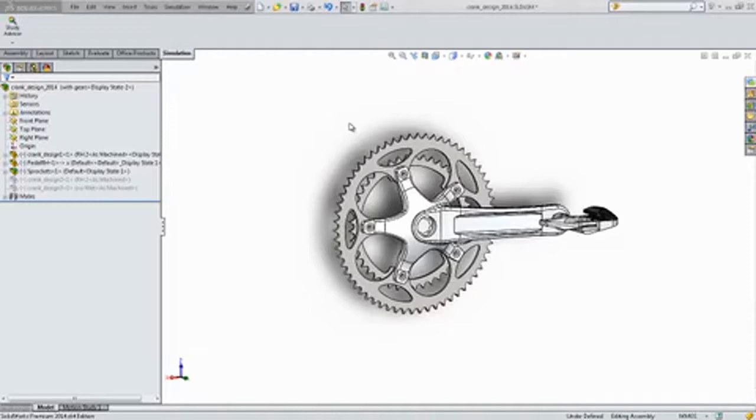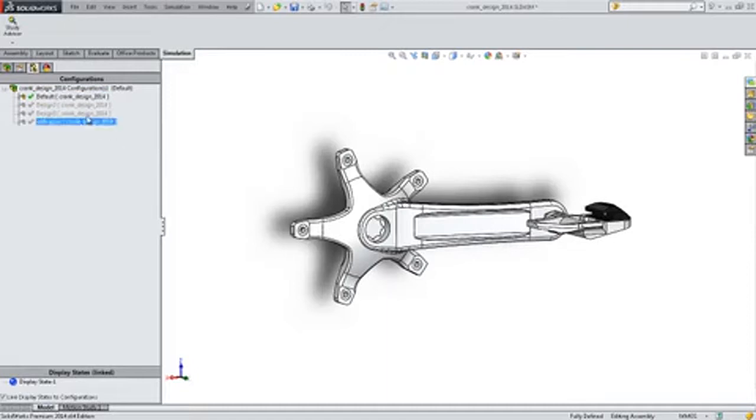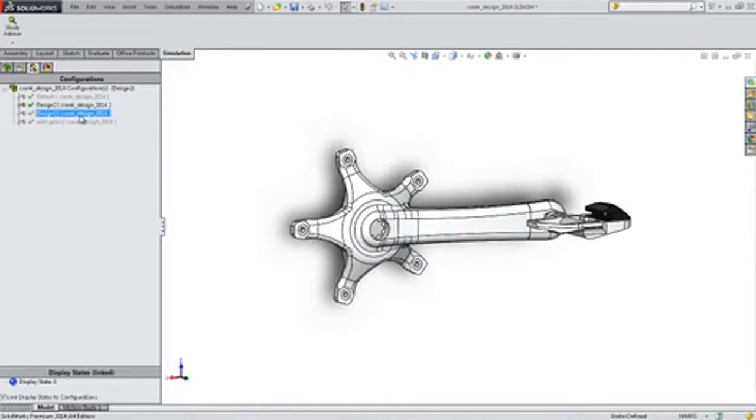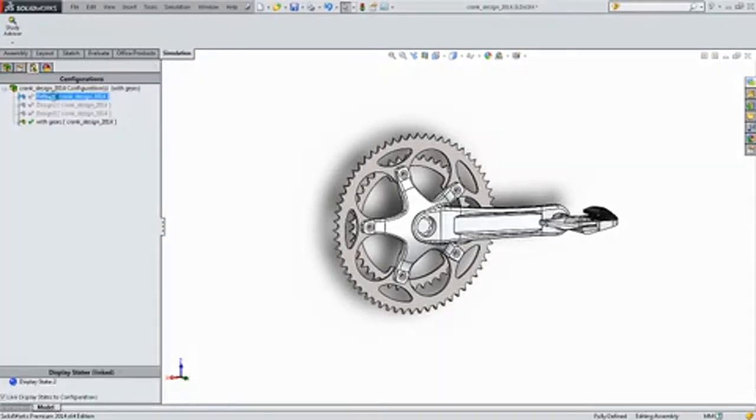Okay, so this presentation focuses on investigating the performance of components using a bicycle crank as an example, what you can see on the screen now. Of course, when designing products, knowing if it will work is critical, however, knowing how long it will last is just as important. And the strength of most materials reduces under repeated loading. This means that over a period of time, even a load well below the yield strength will cause a part failure. This behavior is commonly called fatigue.